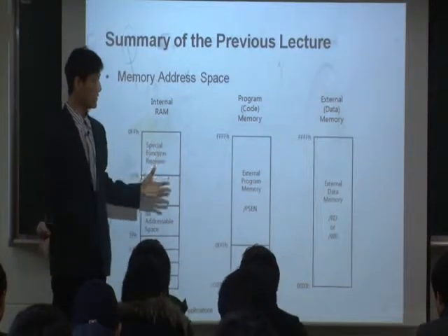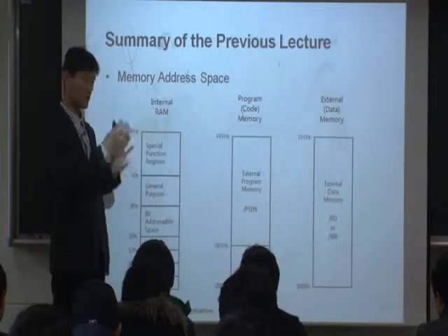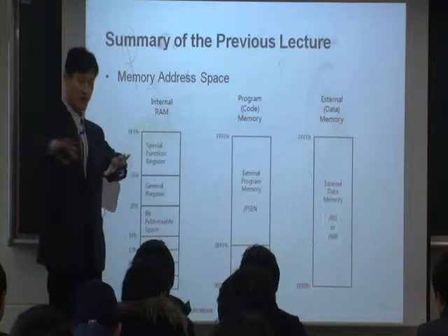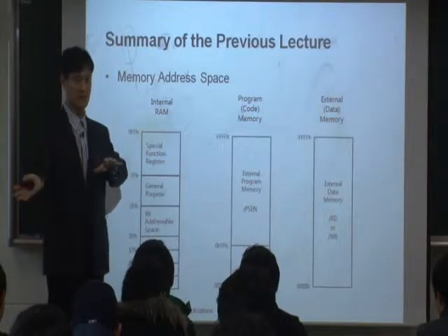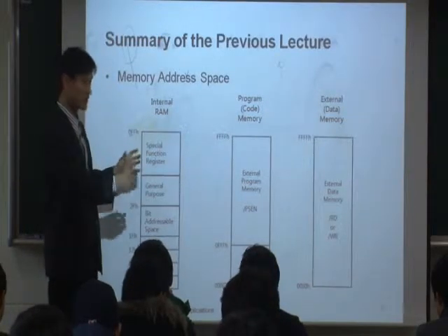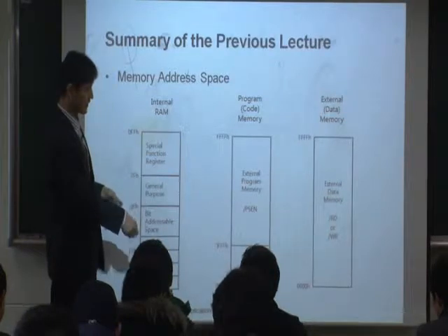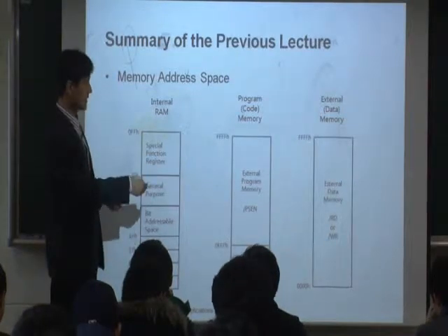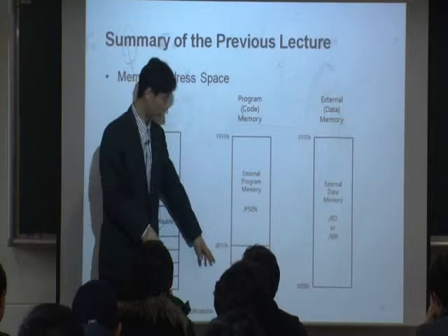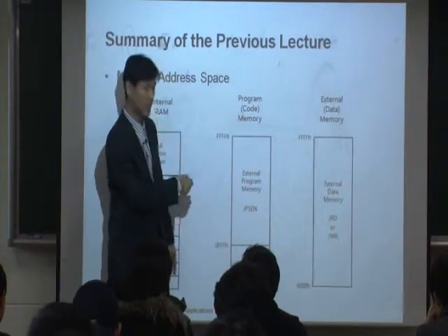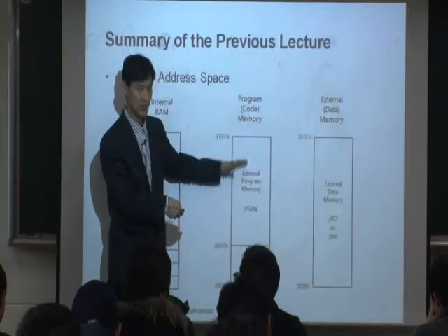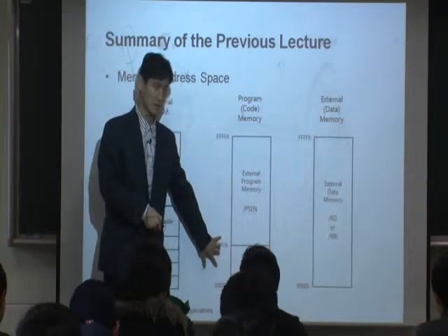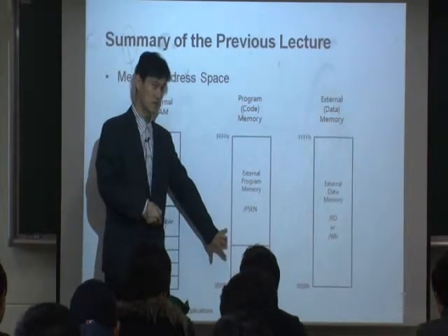And in this area, let's say we build 100 houses. Okay, all the other area, it's still empty. So those 100 houses is like you put 4K memory. All the other 64K minus the 4K, it's like empty right now. Okay, we only have a 4K memory mapped into this address.